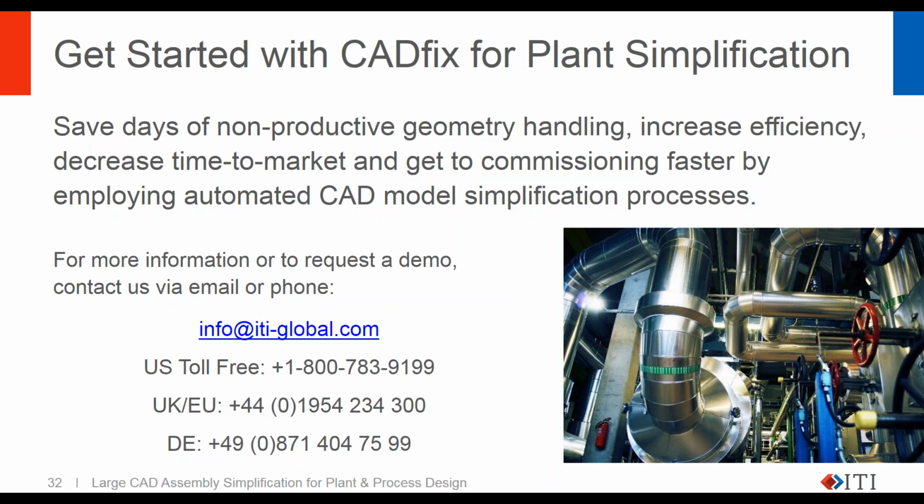Actually, can I just get that last question? Sure. On the hole removal, with the automatic simplification, we do have a whole list of options which you can turn on and off. So you could turn off the hole removal and it won't touch any holes. And you also specify diameter.